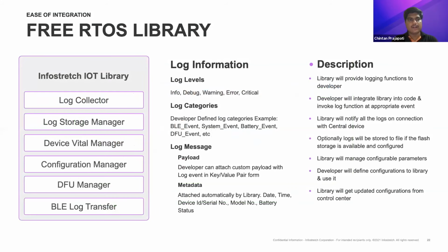This is the overall introduction of our Infostretch FreeRTOS library. This FreeRTOS library mainly needs to be integrated by developers into the microcontroller firmware. The responsibility of this Infostretch library is to collect the logs or events defined by developers. The second component, the log storage manager, will store that data on local storage until it gets synced to the mobile application or hub.